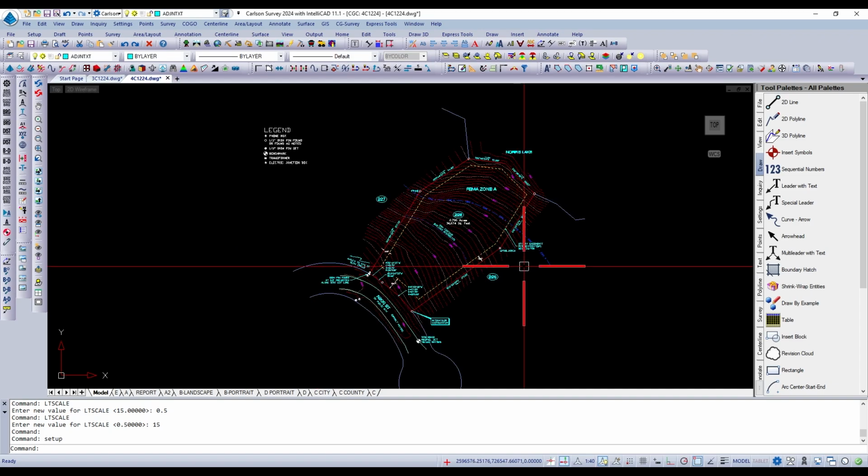So when we're drawing in CAD, before we begin drawing anything, we need to decide what it is that we're drawing. And what we draw determines what our active layer is going to be. This drawing here has no buildings on it, so it's fairly simple, although it has these contours. It doesn't have parking stripes, a lot of things like that, so it's a relatively simple drawing.